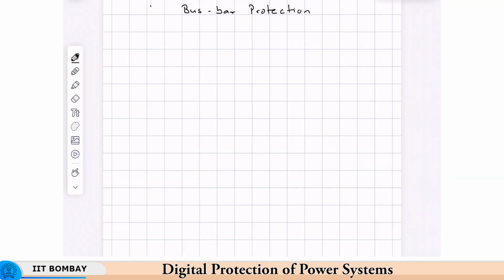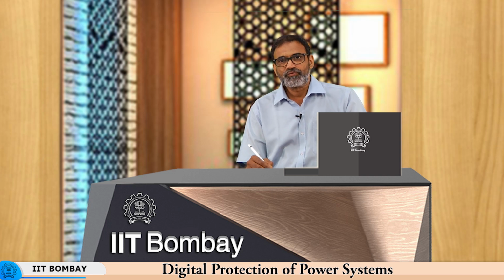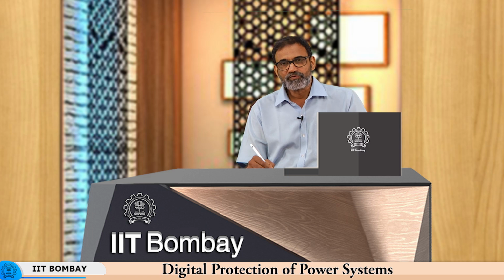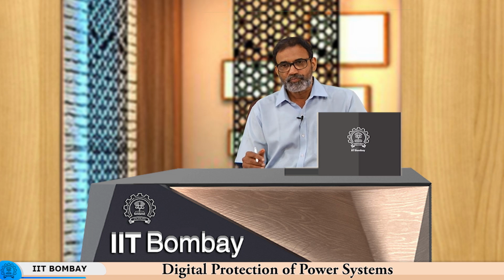So, a bus bar will exist in virtually any network. It is where power is distributed. You have incoming feeders which bring power at whatever voltage level. It could be at even a low voltage level like 415 volts or 11 kV or 33 kV or even very high voltages like 400 kV or 765 kV. So, wherever there is need to distribute power, meaning there are a few circuits which are bringing in power and few circuits which are taking away power. It could be transmission lines, feeders, transformers. A bus bar arrangement is required to distribute the power.